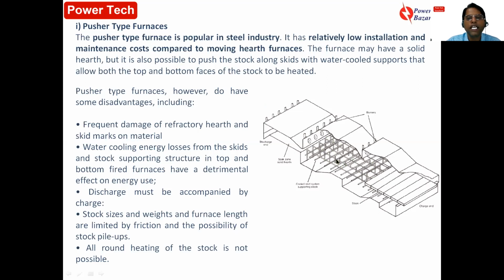Now, these skids also need to be water cooled because they are exposed to very high heat, but it has some disadvantages like frequent damage to the refractory hearth. Since the material is moving, friction is there, so the skid refractory hearth gets damaged.